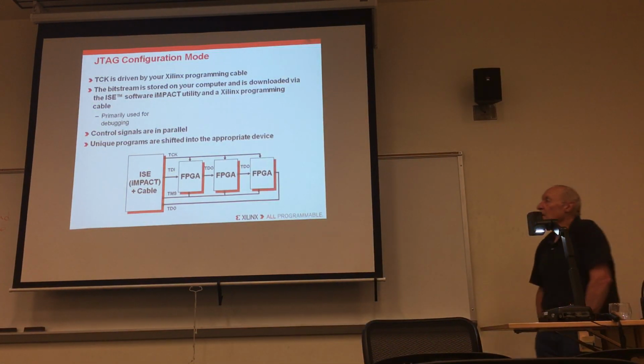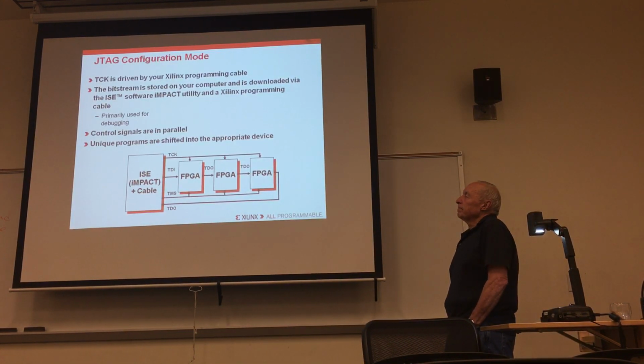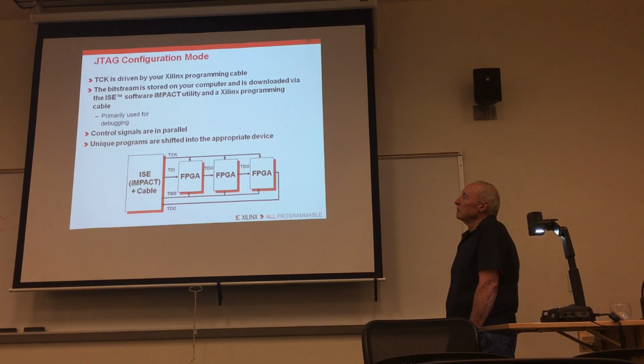After the JTAG node has been identified by the FPGA, the JTAG pins become activated and the JTAG interface is used as a communication channel for the FPGA to be configured. This channel can also be used to create a boundary scan chain. The boundary scan logic is dedicated as part of each Xilinx FPGA and has all the mandatory elements to suit the IEEE standards. The JTAG mode allows the user to easily cascade any number of FPGAs into one chain for programming or debugging. JTAG mode allows a bitstream to be downloaded to each of the FPGAs in the chain with only a programming cable and a 4-pin JTAG header attached to a demo board.